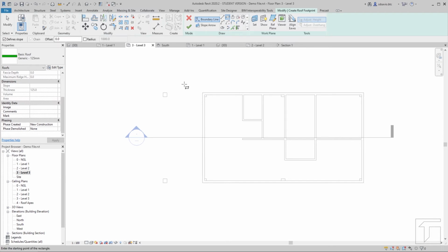Afterwards, since normally roofs have eaves, right? The standard is about 600 millimeters. So to instantly draw the eaves, or rather the extension of 600 millimeters of the roof, we'll now add an offset to that. On the options bar, we have the offset. Let me type there 600, and that should offset instantly by 600. If I click on the corner of this column, notice that it offsets automatically the guideline of the sketch by 600.